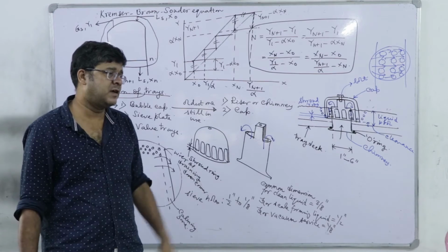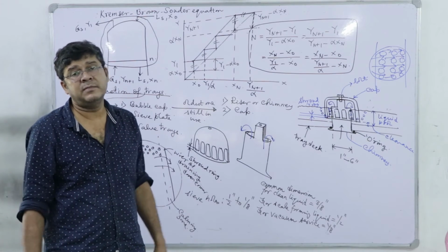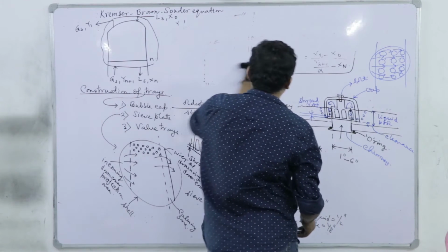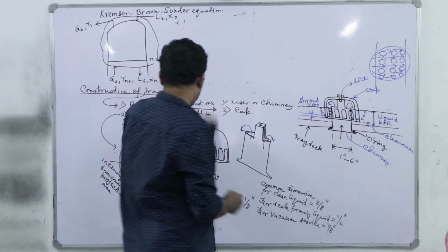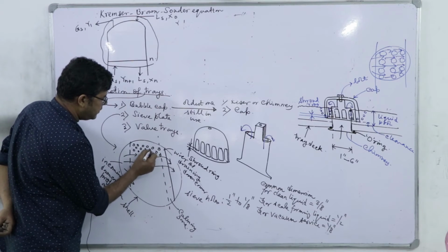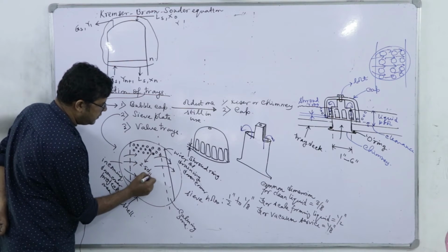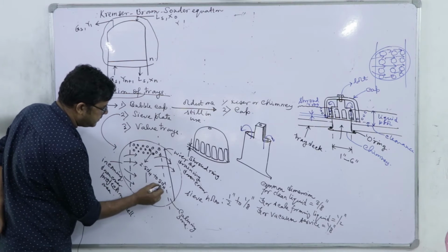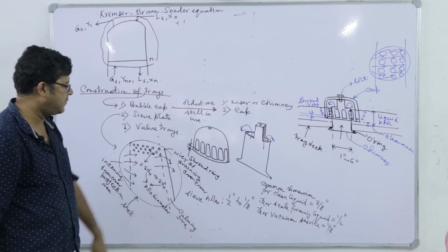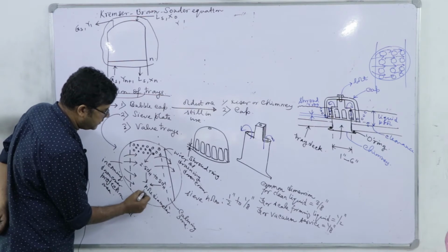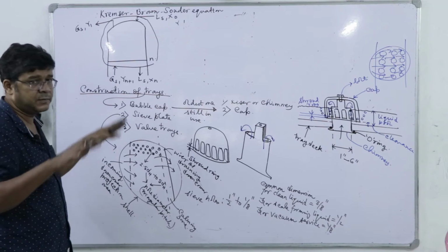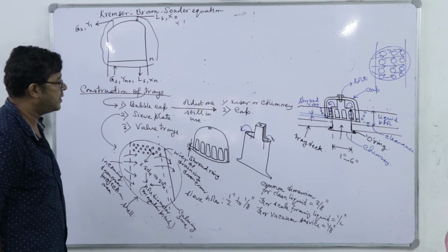Even if the gas charging rate in that column drops, it will adjust the same gas velocity as with which we have designed the column. How come it is possible? So, valve tray, you see, and another additional specification regarding the sieve, that pitch, that is hole to hole distance, is 2.5 dH to 5 dH, where dH is the hole diameter. Right, and the hole diameter may vary, and accordingly we have to adjust this pitch, and it is triangular pitch. We generally recommend for the sieve tray, otherwise we will not have high interfacial area being generated between this gas